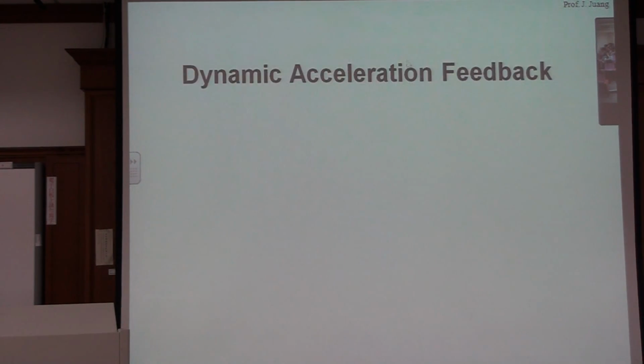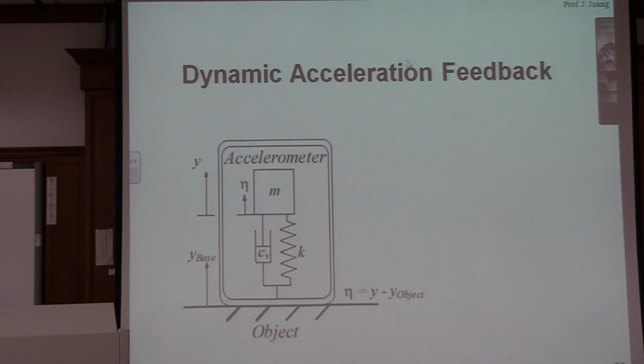All right? And now let us look at the accelerations. What is the difference between displacement and accelerations? The acceleration means the w double dot. And these accelerometers, if you look at them, are just a TMD. True. All the accelerometers are designed like this one, unless there is something new, some new one a little bit different, with piezo materials. But the conventional accelerometer is just a TMD.